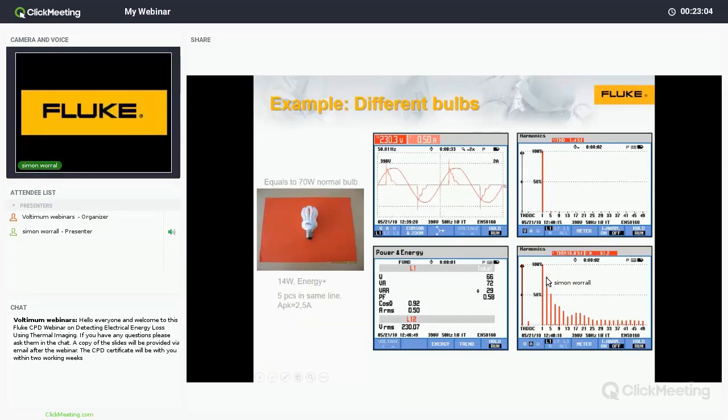And if we look at this harmonic here, the third, we've got 75–80% of third harmonic, which can cause other problems as well as heating. But why do we do it? Well, we've reduced 291 watts to 66 watts. So our energy bills will improve.